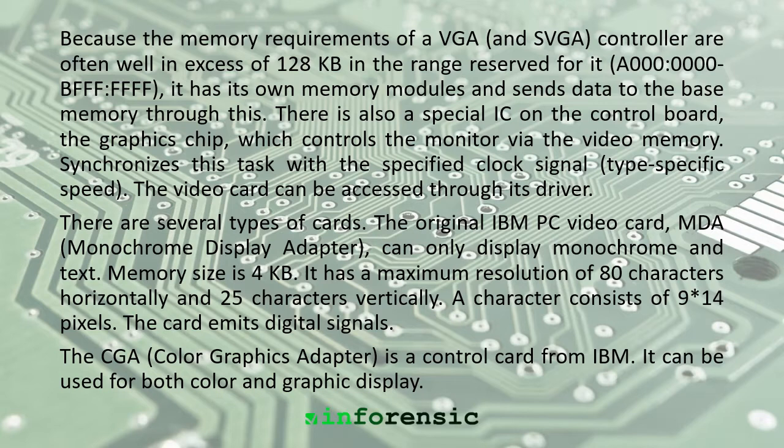The original IBM PC video card, MDA, monochrome display adapter, can only display monochrome and text. Memory size is 4 KB. It has a maximum resolution of 80 characters horizontally and 25 characters vertically. A character consists of 9 × 14 pixels. The card emits digital signals.